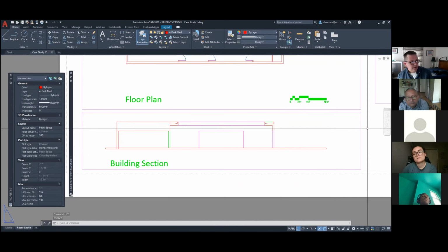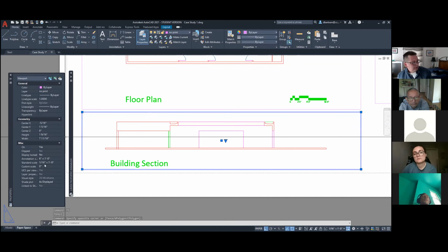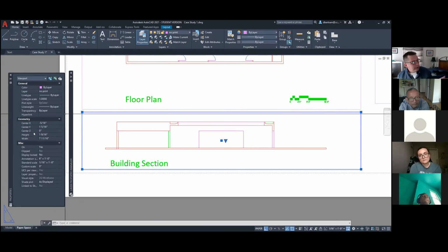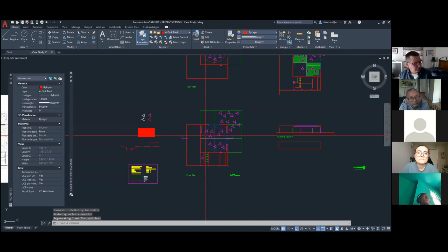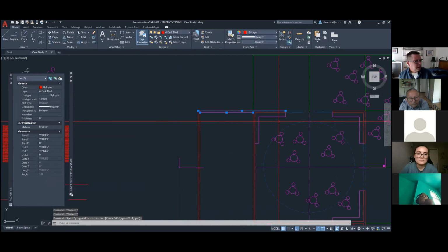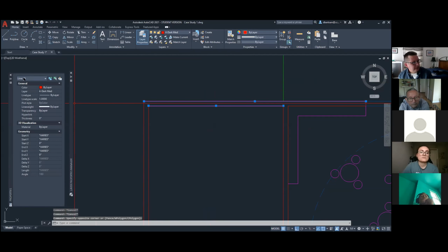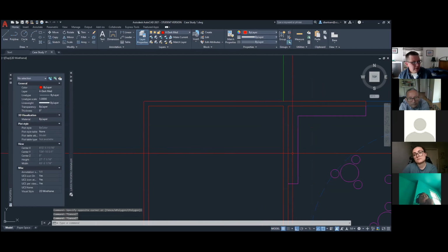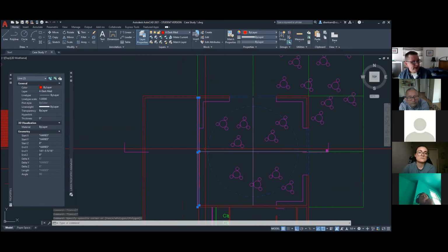Paper space. And when you're messing around adjusting viewports, it's always good to keep an eye on things down there. So this property box should always be there, in my opinion. It's just full of important information. If nothing else, when things are weird, I would come here and just confirm that it's only 2 lines. If something wasn't printing right, there might be another line buried under there. So I always like to see that this is confirming what I expect I drew.